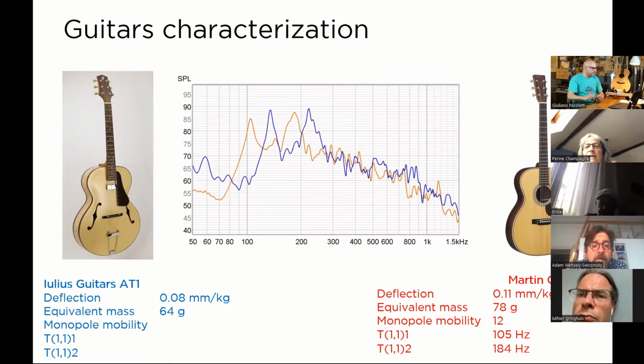So we have this archtop guitar designed following Benedetto's rules, if you want. This is a very standard 16-inch archtop instrument with maple sides and back, spruce top. The thickness is around 5.5-6 millimeters on the top of the dome, down to 3.5 millimeters on the recurve of the guitar.